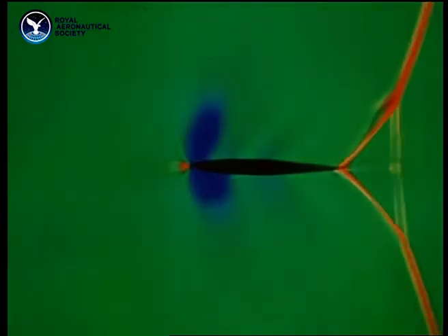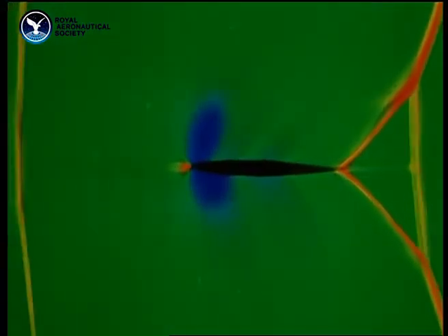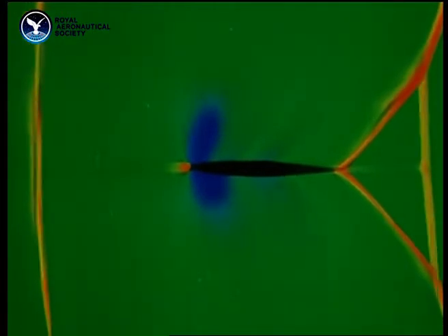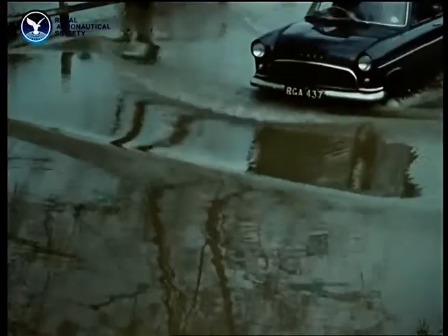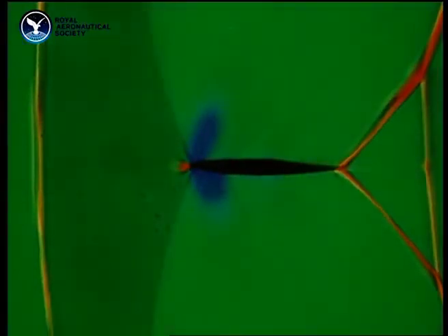The flight Mach number has just passed Mach 1. The free air stream is supersonic now, and another shock wave appears in front of the wing, the bow wave. It's something like a bow wave on the surface of water. As before, the supersonic regions are lighter green.